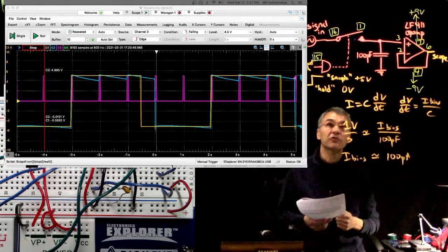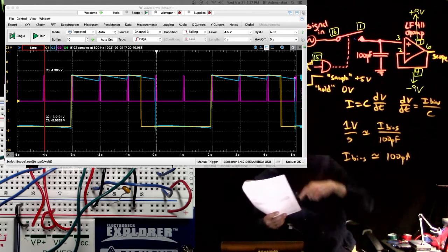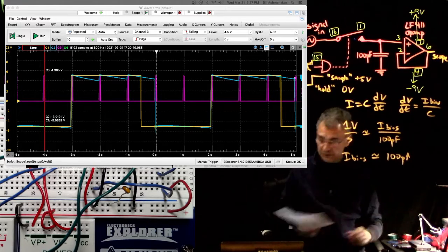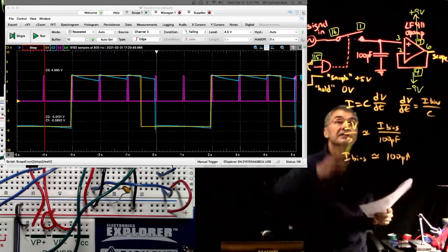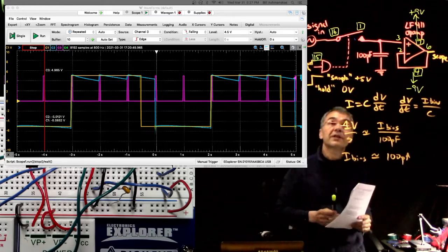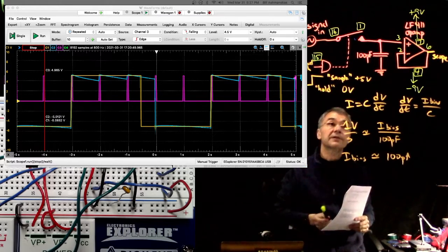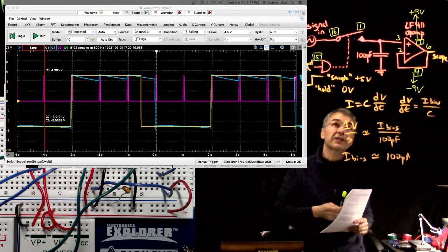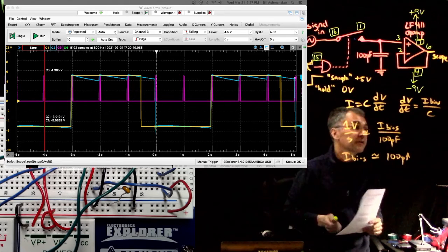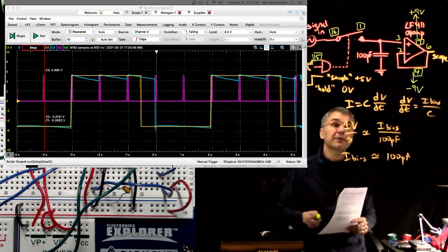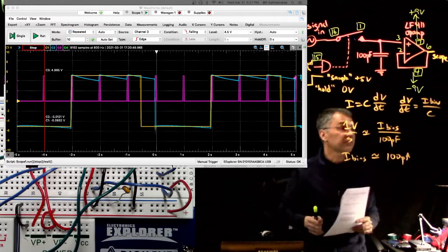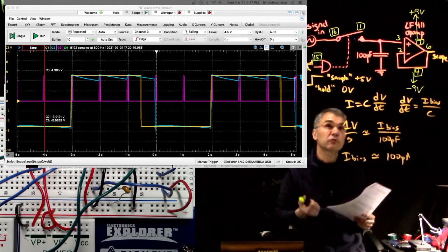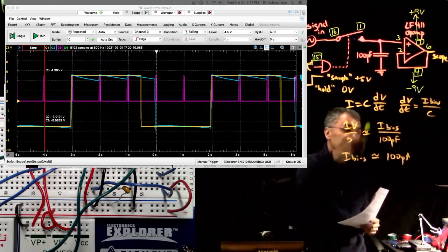I guess we didn't check the resistance of this analog switch when it is open. We checked the resistance when it's closed, but we didn't check the resistance when it's open. So I'm not sure how to quantify that with what we measured already. But anyway, I think this is an adequate explanation. In principle we should rule out other explanations, but this seems pretty good.